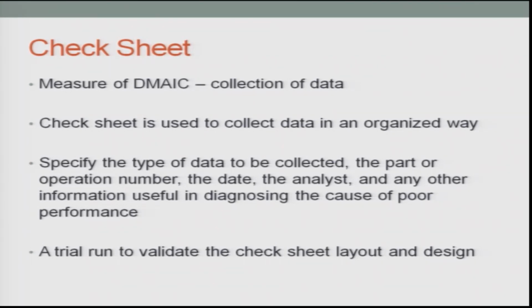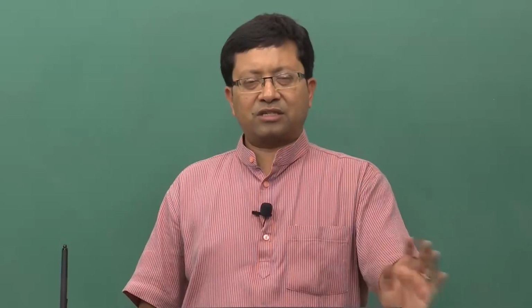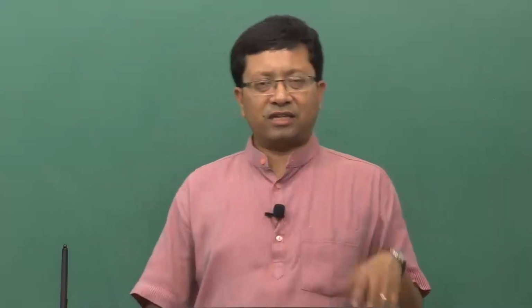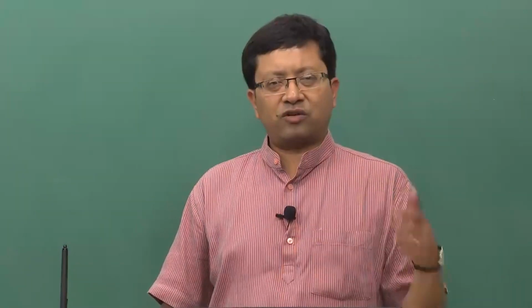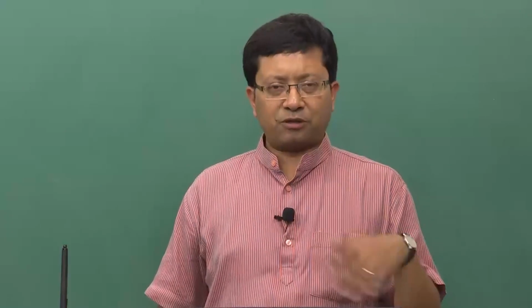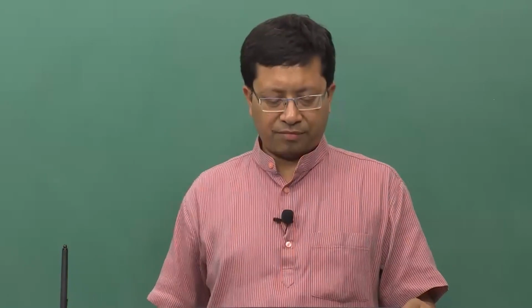A check sheet is used to collect the data in an organized manner, specify the type of data to be collected, the part or operation number and the date, who the analyst is, who collected the data, how many different points were collected, at what point of time they were collected, and all the information is important. A trial run to validate the check sheet layout and the design can also be taken in order to accurately find out how good or how bad the data being utilized is. Is it spurious, or has the data collection been done in the best possible manner? Those have to be checked.